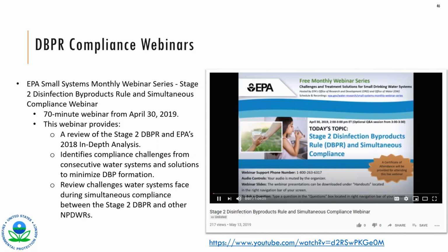This webinar specifically focused on the DBPR portion of the analysis, since it was found that the highest number of health-based violations for community water systems were Stage 2 DBPR violations, and the majority of those systems and violations were consecutive systems. So this webinar focuses on reviewing the compliance challenges that EPA noticed during this analysis and provides solutions to help consecutive systems minimize DBP formation.